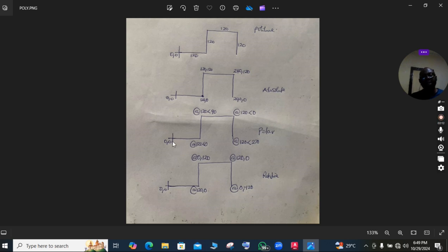If you now want to use the polar method, you click on polyline. It will tell you to specify the first point. You put 0,0, assuming you are starting from the origin. Then specify next point. The method here is to type @, because you are going to specify this point relative to the previous one. It will be @ distance < angle, the distance and the angle.